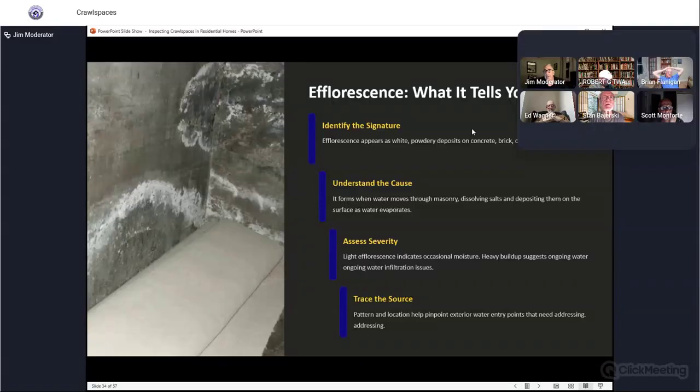So this is kind of like a basement, right? When you see the efflorescence on the foundation wall, it doesn't tell you exactly what's going on, but it certainly tells you that wall's being saturated with moisture. If that's the least of it, that's one thing. But generally, if you look around at any wood that's touching the ground, you see water stains, or there's probably more to it than that. But that's enough for me to say that there's evidence of dampness and/or seepage in the basement.